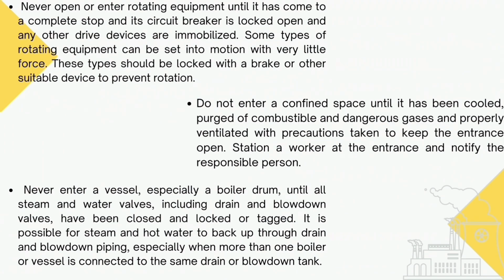Never open or enter rotating equipment until it has come to a complete stop, its circuit breaker is locked open, and any other drive devices are immobilized. Some types of rotating equipment can be set into motion with very little force. This type should be locked with a breaker or other suitable device to prevent rotation.